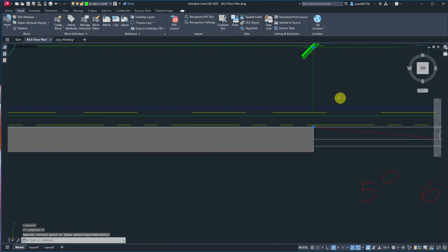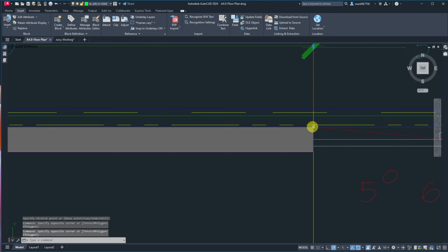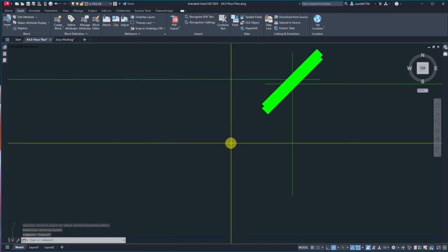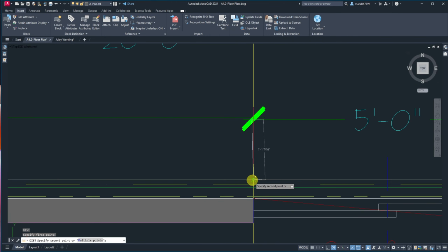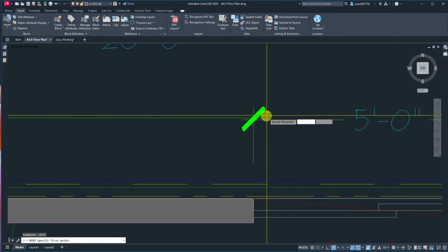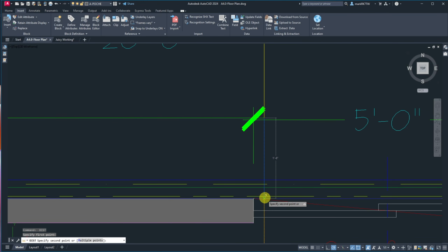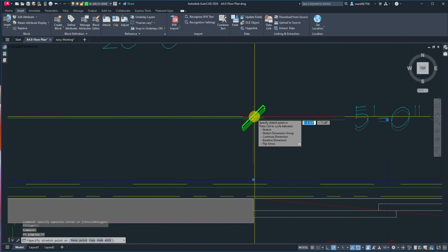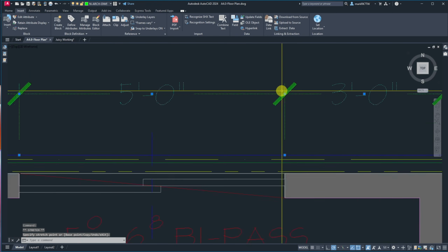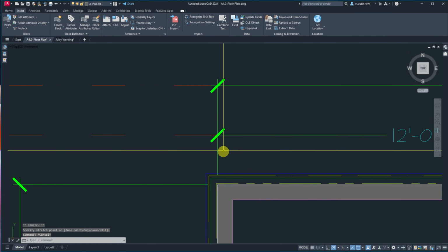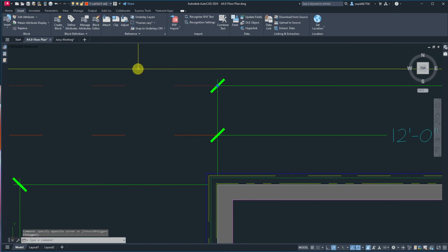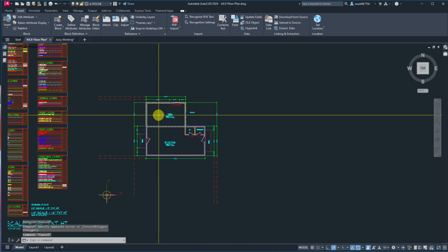And I want both of them to go with me. Now, I can tell you one of these is wrong. Probably this one because it's by itself, but what I do is I'll check it. This distance should be 18 inches to there, and it's not. So, it looks like the far one is correct. Yep. And these two are not. So I'll just pull that out. Correct this one. And we're good to go. Yeah, this was on the line. That's what these are here. They're called layout aids. So they won't print either.